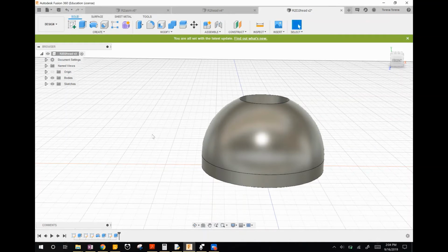And that's it for the first part of this tutorial. So just to review, so far what we've gone over is how to make sketches, and then how to turn those sketches into three-dimensional volume using an extrude or a revolve, and also how to remove volume by using an extruded cut. We also learned how to work with our design history, and how to roll back to previous states and roll forward again.